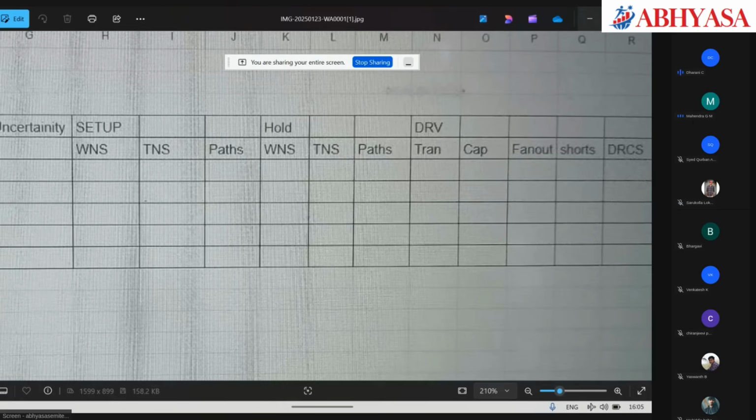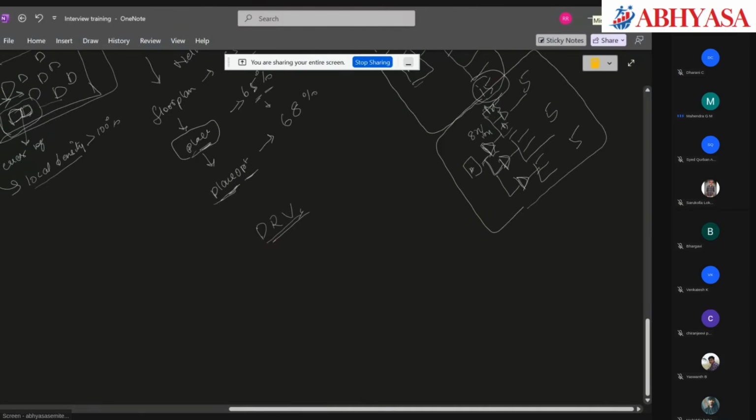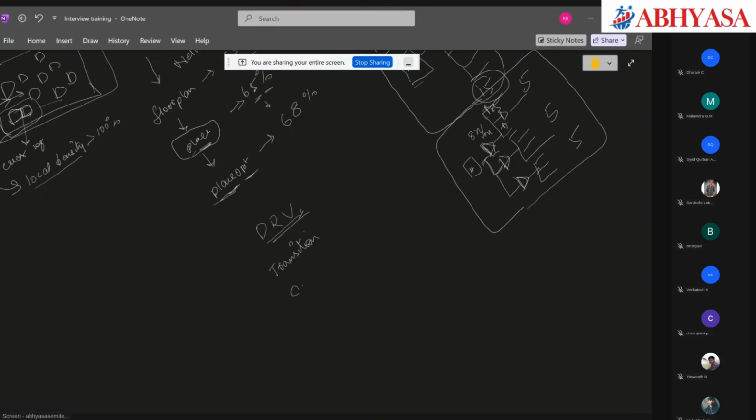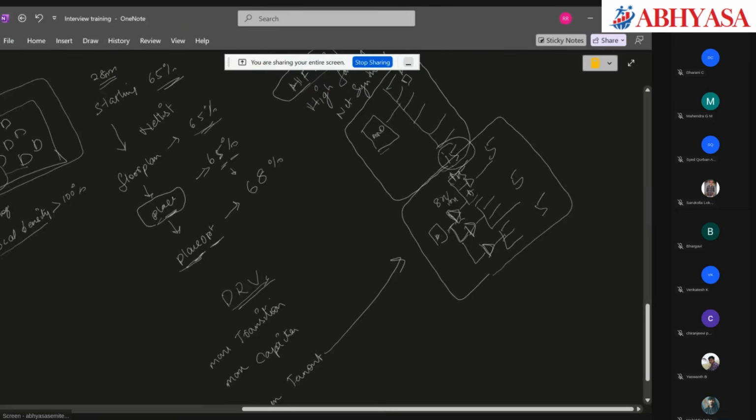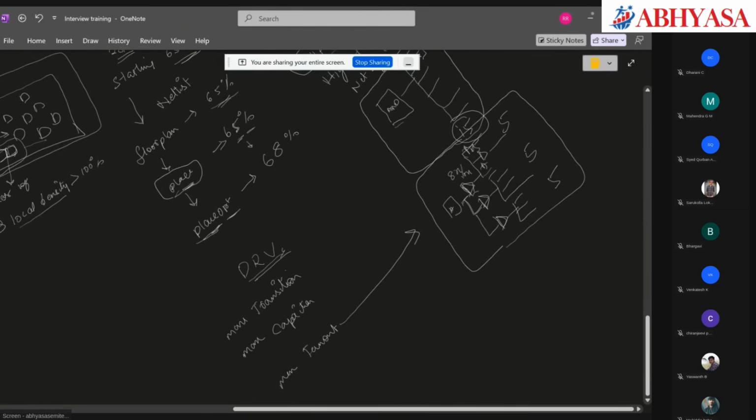So at place stage, transition fixes and capacitance fixes and max fan out. This we have anyways seen. It will fix the fan out using HFNS.